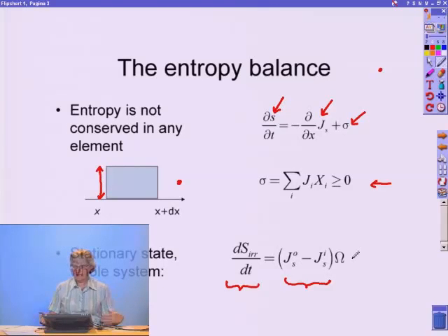So we have the entropy balance as a balance equation with more detailed information about the entropy production, and that makes an additional equation that you can use together with what you have used already. Maybe you have used the mass balance, the energy balance and the momentum balance to calculate your system so far, I think. And now I'm saying that we have an extra opportunity. We can use the entropy balance also to solve our unknowns or to check on our system.